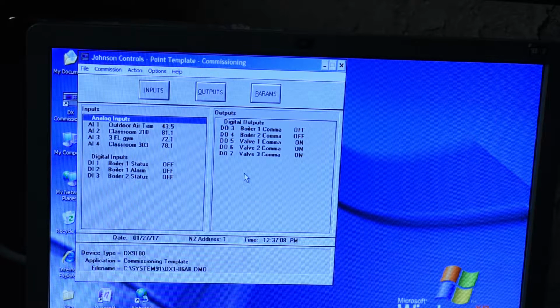So my experience here, setting these set points to 75 pretty much balances the ambient temperature where most people, staff, students, and the public are pretty comfortable. So at this time, I am in the commissioning mode, testing the system I just previously programmed.